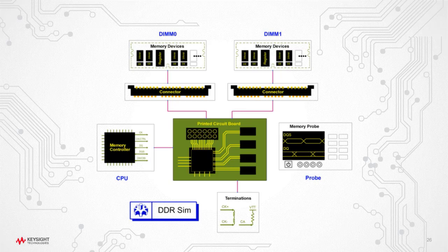Now there's one more thing I want to bring up about this. We talked about DDR bus sim being a statistical simulation solution, and even when we move to DDR5 with IBIS AMI models, that is also based upon the idea that the channel is linear and time invariant. Many of the simulations you do for power awareness, things like synchronous switching noise, are most definitely time varying. So you might have a question in your mind: how am I going to do these types of simulations for DDR5?